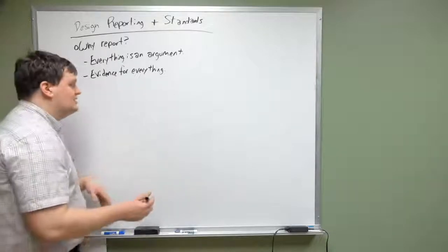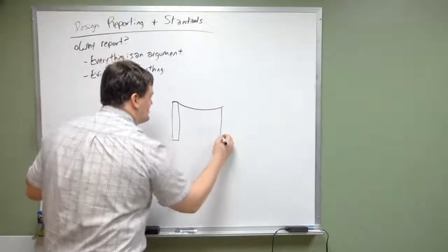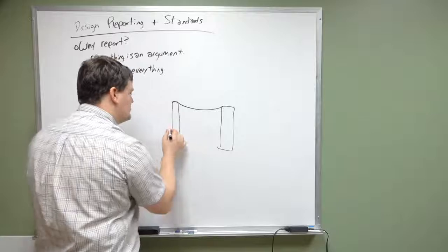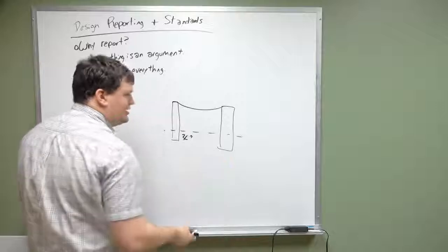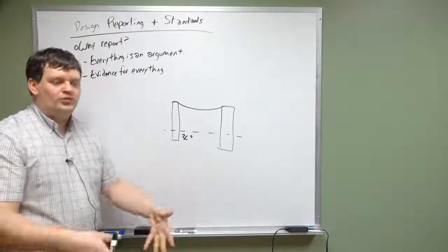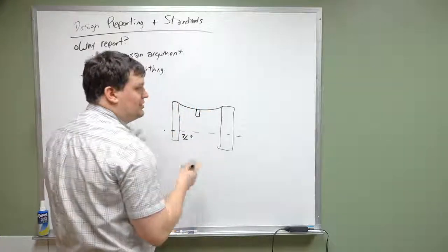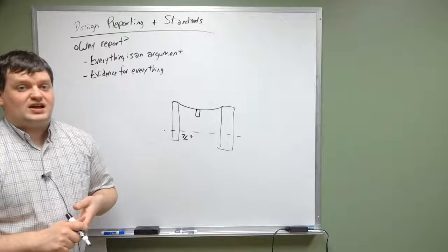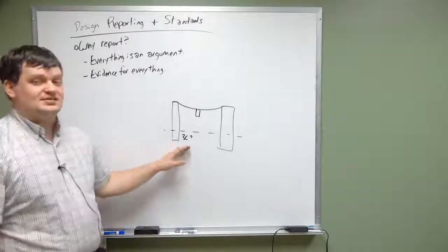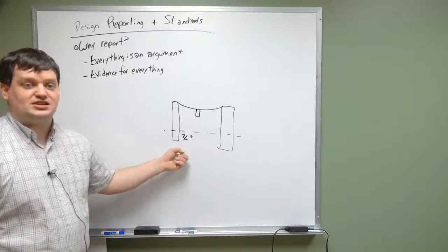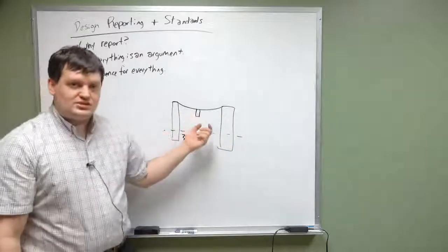If you design a system, and let's say you just take a 4x4 post, extend a string between it and another 4x4 post, maybe you embed those 4x4 posts 36 inches in the ground, just hard pack, dig a hole, fill it back in with dirt, you extend a wire between them and then hang a light from the middle. You should be able to justify every one of those decisions. Why is the embedment depth 36 inches? Why is it that you chose to have that be 36 inches deep? Why did you pick a 4x4 post? Why did you choose the rope that you did? Why did you choose the light that you did?